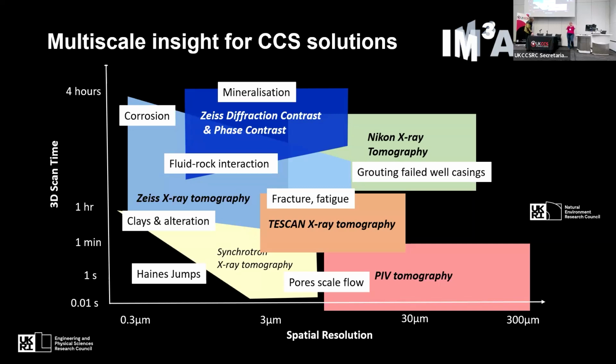For the crystallization, we're generally doing it numerically in the imaging space. So we grow by increasing the number of pixels of an object in a particular way, and we can link that to the simulation of the flow, which is normally a combination of lattice Boltzmann and normal Darcy-Navier-Stokes flow models that we use through these structures. It depends on the complexity of the system and the problem we're trying to tackle. Okay, so the simulations actually captured capillary dominated flow. Yes. Okay, thank you.